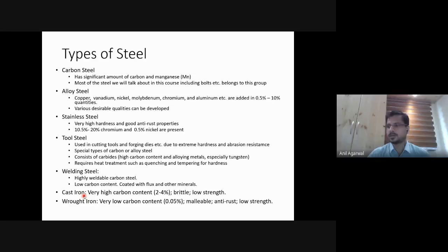Decorative, sir. Decorative. Railings. Railings, yes. So if you go to any old cities, say Paris or London, and you see those lamp posts, right? There is a lamp on the top and there is a kind of pole, and that pole would have some decorative features, and all that is made with wrought iron. Because it was very malleable, they were able to heat it a little bit and deform it into various shapes and forms. And benches, even the Eiffel Tower is made of wrought iron.